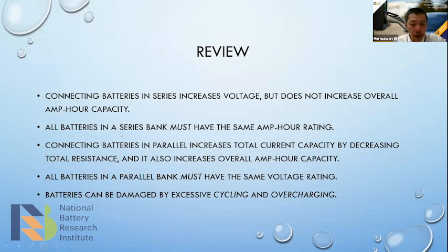And then, in a bank, all the batteries inside the one bank must have the same ampere hour. Most battery pack companies or battery pack factories do grading. The grading is needed to match not only the ampere hour, but also the same internal resistance and similar voltage within one bank. That avoids problems of higher or lower values, or differences, inside the pack.